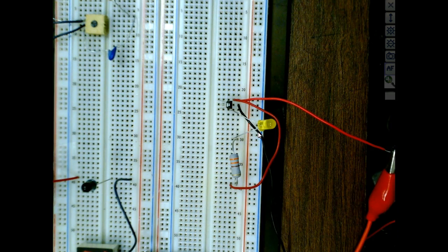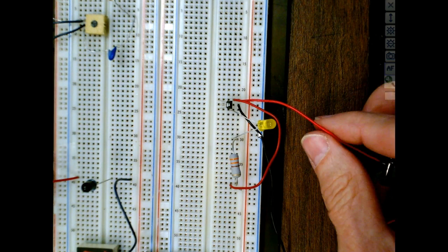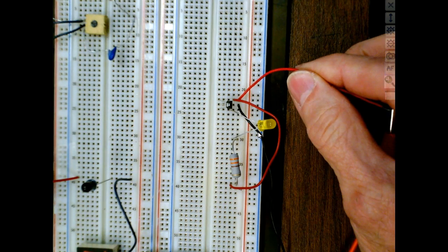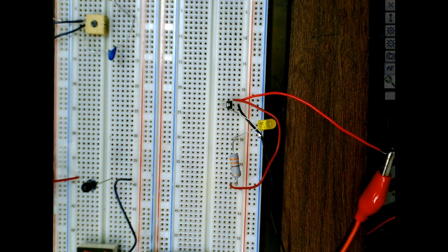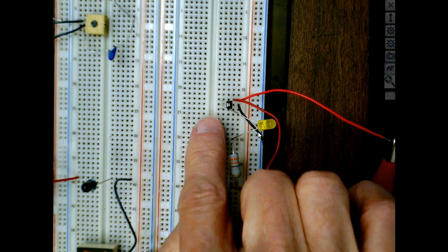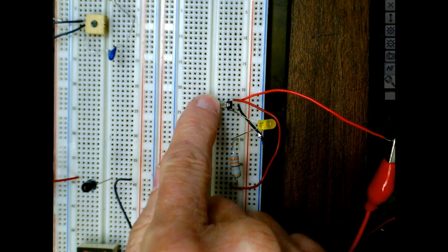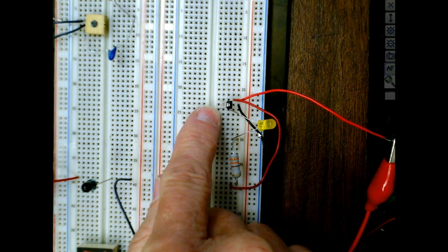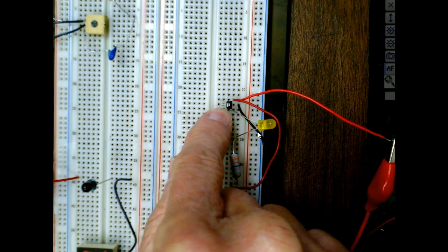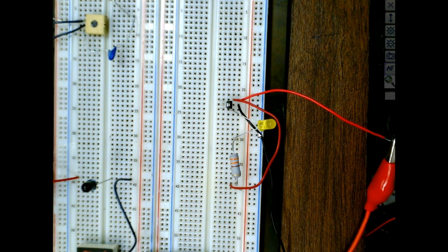So a Hall effect sensor senses a magnetic field, but it's an electronic circuit, which means it's got to have what? It's got to be powered. So normally these guys have at least 3 leads coming in. Sometimes they have 4. Common is 3. We have a power pin, then we have a common pin, and then we have a what? A signal pin. And this is a latching. I don't have any analog. I need to order some.